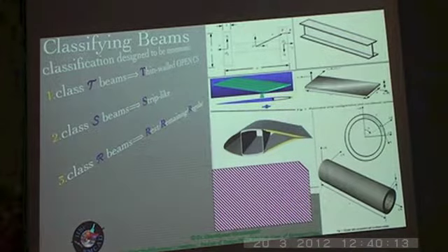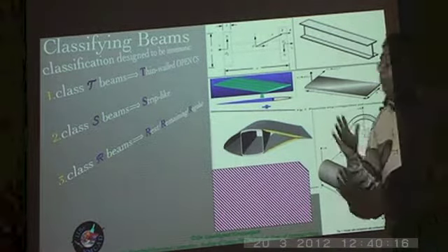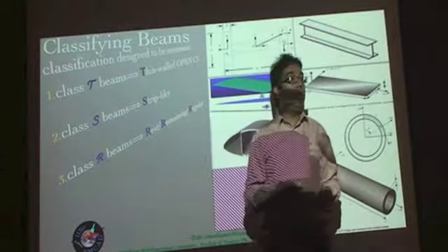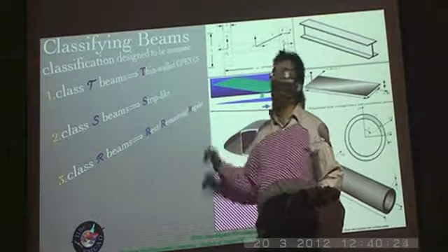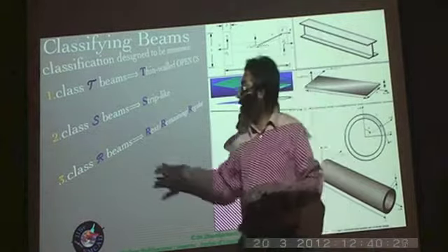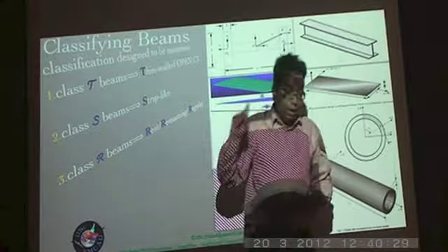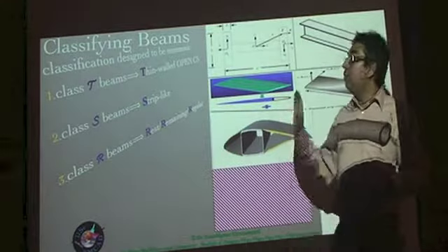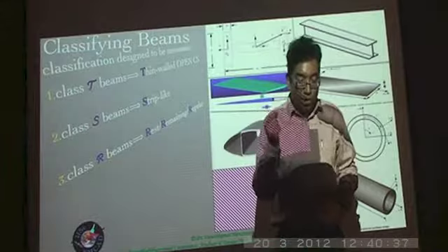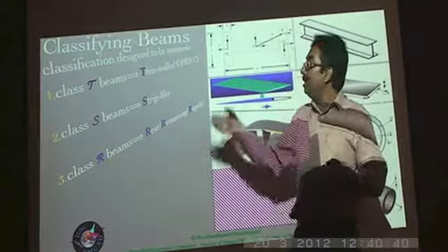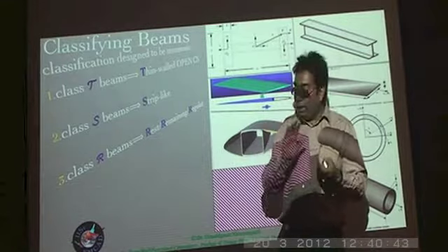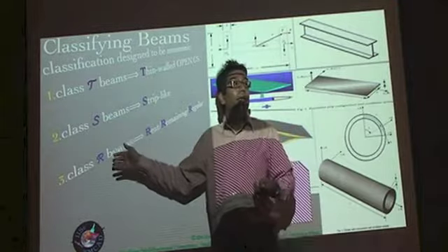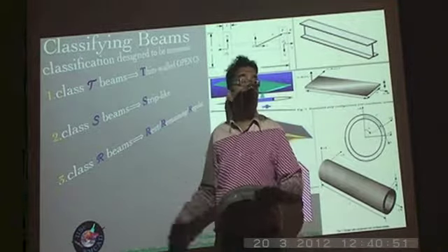Finally, you have class R beams, by which we mean all the rest, all the remaining beams, all which are neither thin-walled open cross-section nor are they strip-like beams. Anything else, rest or remaining or regular, so-called regular cross-sections that we are basically clubbing into our class beams. So they include solid cross-sections and thick-walled closed cross-sections, but as I said, the thin-walled closed cross-section is a special case which does not actually figure into any one of these. At least up to the 0th order approximation, of course, you can put it in the R class beams, and of course all can be put into that.